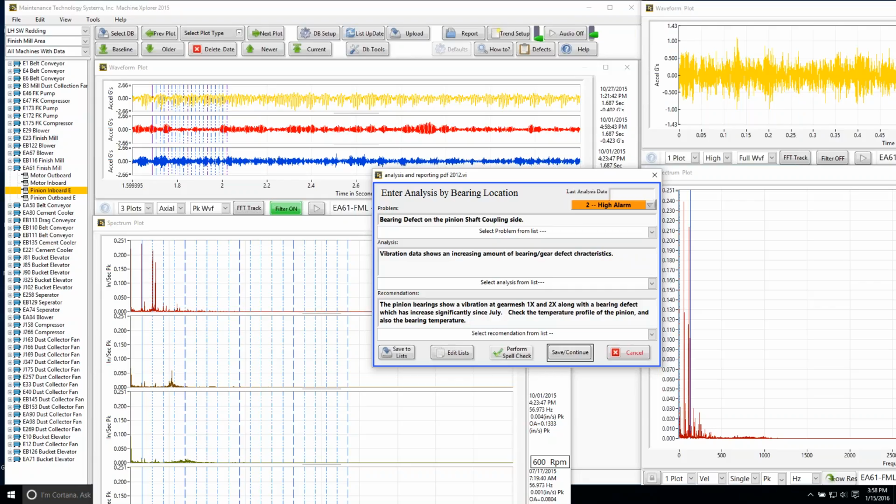The other side of it is, this is just like your ball mill out of the slag plant. It just has a pinion driving a ring gear, so you expect to have a little looseness in the rattling of the balls and so forth. So I typically don't talk about looseness on these things because of that. All right. And they probably wouldn't do anything about it anyway. Well, they're concerned about it, but so I've just done these guys.